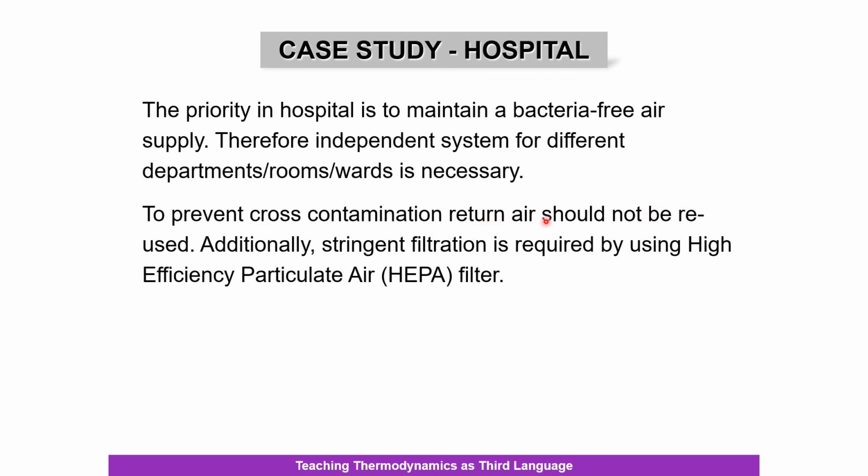So they usually do not use it, which is why they mix it with fresh air. And you also have HEPA filters. So what is a HEPA filter? You want to filter the air so that you can remove the bacteria, viruses, and so on. So they use a high efficiency particulate air, HEPA, filter. This is just a brief introduction to how they use air conditioning in a hospital.